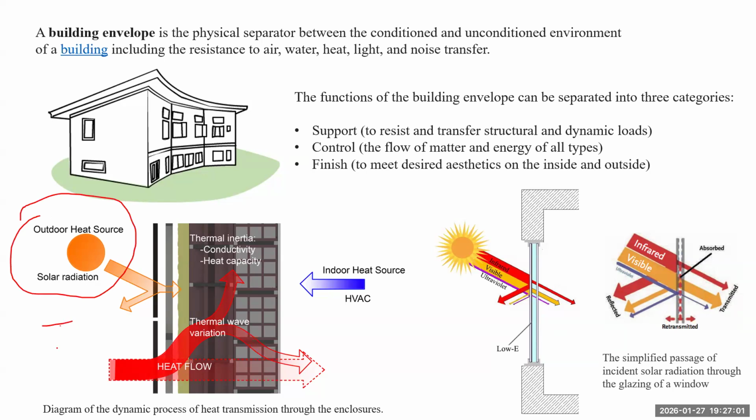If this side is high temperature and this side is low temperature, there is heat flow due to the temperature difference, and the wall acts as a thermal regulator. We need to calculate its U value to calculate the conduction heat transfer due to the temperature difference of the two surfaces. But for our buildings, during daytime, our building will also receive solar irradiance.